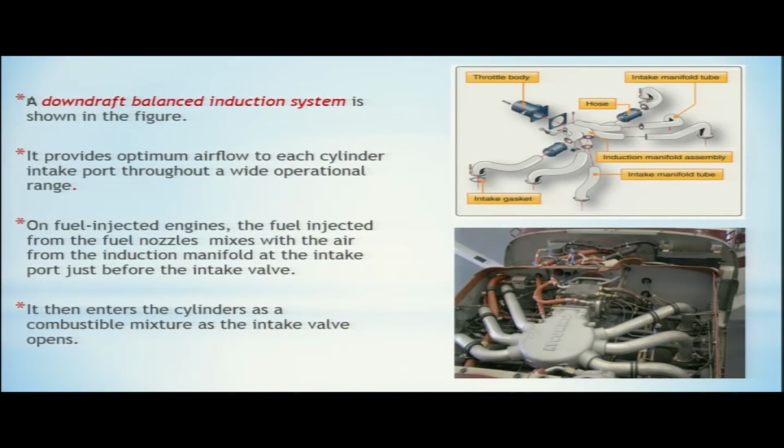Now coming to another type of induction system, this is a downdraft induction system. Here you can see in the figure, this is your downdraft induction system. You can see the intake pipes, they are facing in the down direction. That is why this is called downdraft. It provides optimum airflow to each cylinder intake port through a wide operational range.